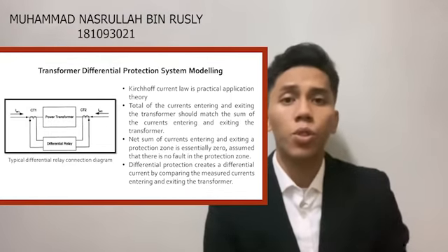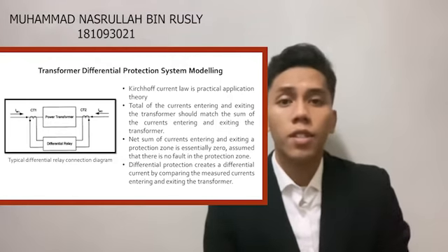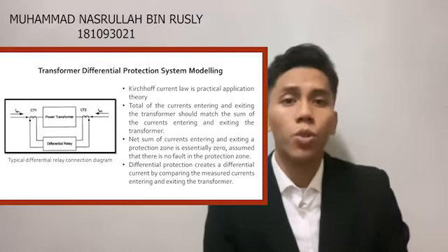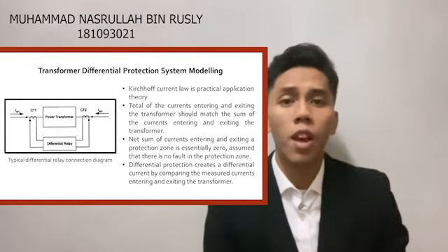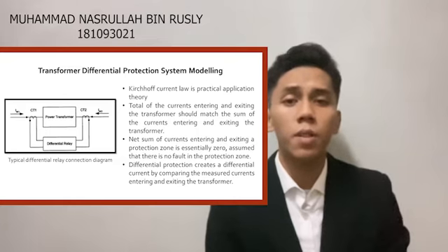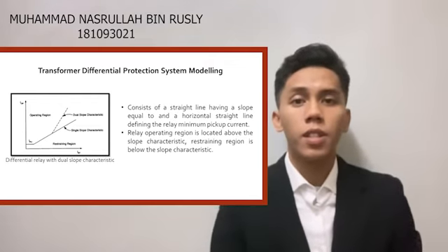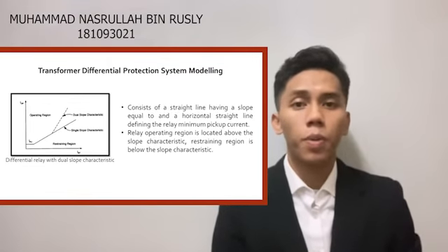Misoperation can occur during transformer energization due to harmonic restraint function failure. An external fault can also cause a misoperation during the voltage recovery period, causing the differential relay to operate immediately after a fault is removed from the system. Percentage restraint differential protective relays have been in service for many years. Differential elements compare an operating current with a restraint current. The operating current, also called differential current, can be obtained from the phasor sum of the currents entering the protected element.